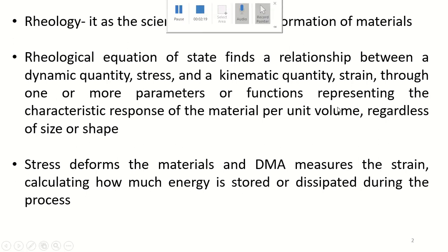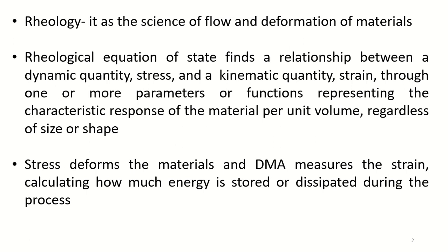While according to N.W. Tschoegl, a constitutive equation or rheological equation of state finds a relationship between a dynamic quantity, stress, and a kinematic quantity, strain, through which one or more parameters are functions representing the characteristic response of the material per unit volume. It is regardless of the size and shape.